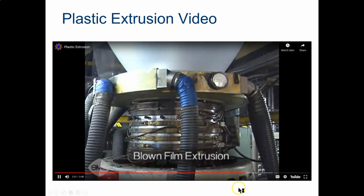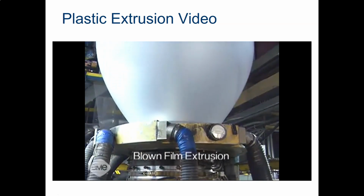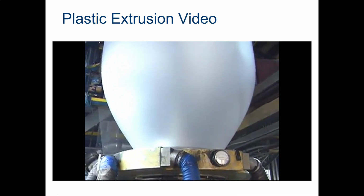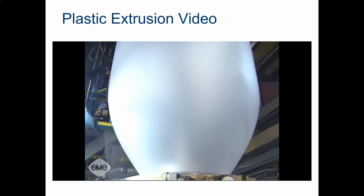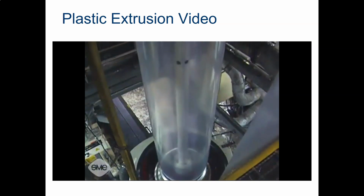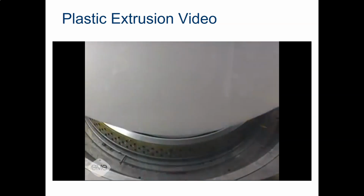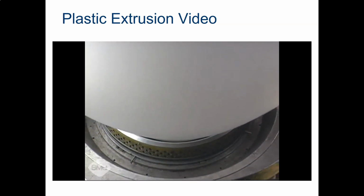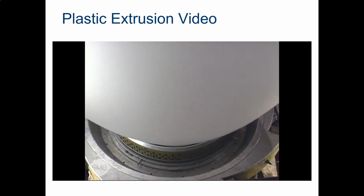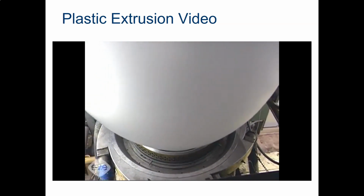The blown film extrusion process uses an extruder to pump molten plastic vertically up through a die having a 360-degree annular opening on its top. This produces a tubular film extrusion, which is subsequently filled with air. As a result, the tube expands out into a bubble, having a diameter larger than the diameter of the annular opening of the die.